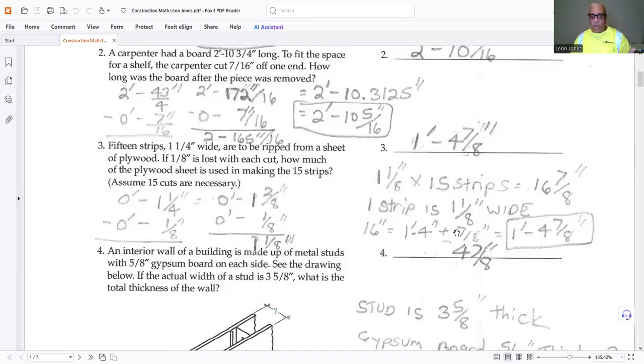And in construction, you're going to do it. Like I said, if you're in carpentry, you're going to have to be understanding of inches. So you're going to use quarters, you're going to use eighths, and you're going to use sixteenths. It's very popular. Now, in engineering, like myself, I'm going to use tenths of a foot, like 6/12. I would call it 0.5, which is half of a foot.